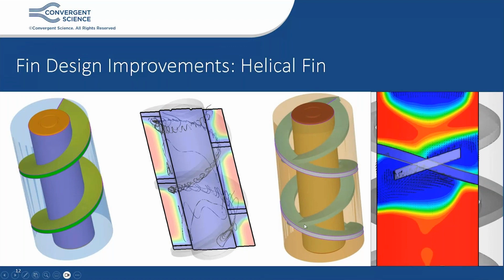Here we employed a double helical design where we sought to change the flow direction of the melted liquid in order to consume the unmelted or the solid phase change material, based on our understanding of the performance of previous designs. As you can clearly see, there's some unused phase change material here.